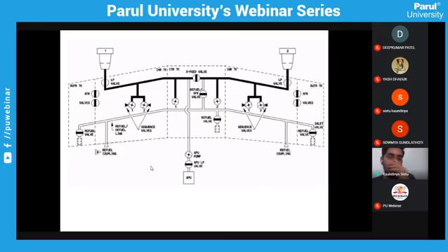In aircraft, every system is doubled, or tripled: if one fails, the other has to take care of the failure. The hydraulic system is a triplet: blue, green, yellow. If one fails, the others will take care, depending on the type of system. Okay, now 1 and 2.